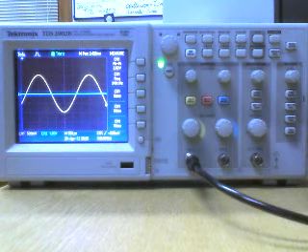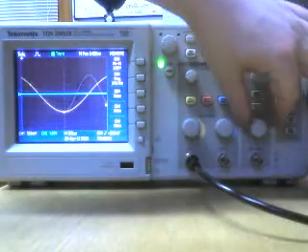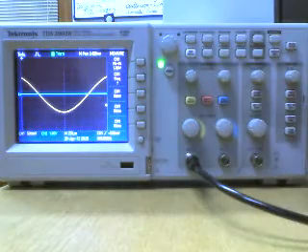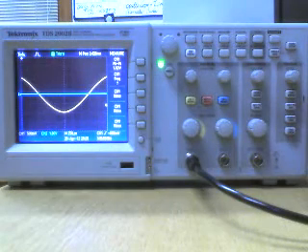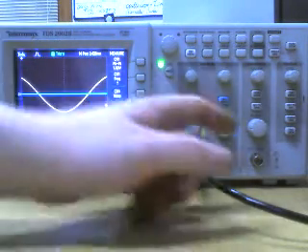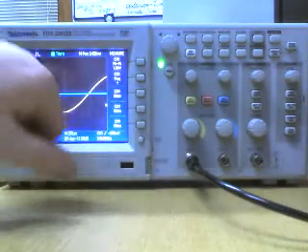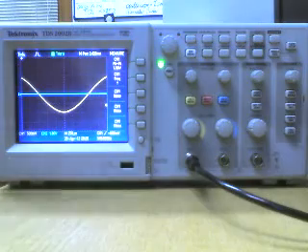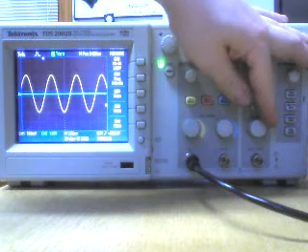It's quite a large value. Okay, large error. Same for time. If you don't have a period on the screen, usually it won't be able to measure the time whatsoever. Sometimes it can, sometimes it can't. It's because the start and stop of the waveform, its cross points, are actually off the screen. It's got nothing to reference any other measurement to, so it won't be able to measure frequency.